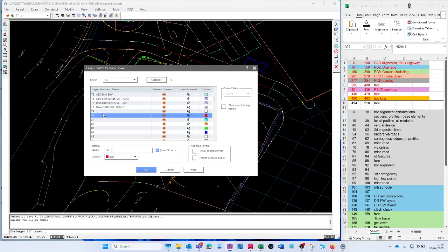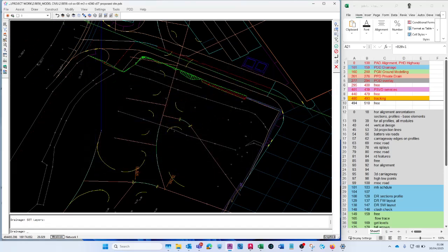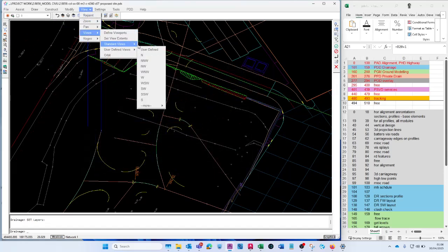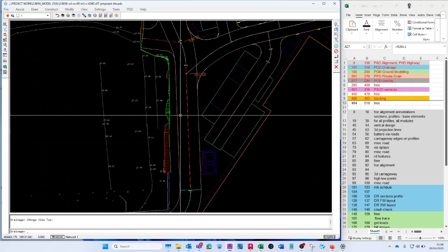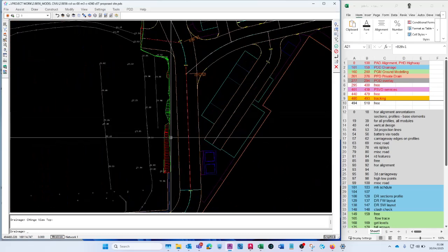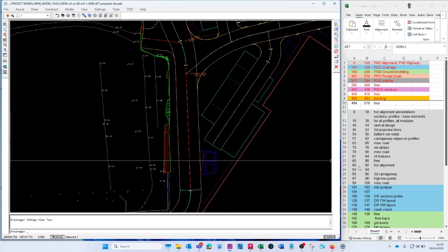so 79 to 80, just some miscellaneous ones. 81 to 84 get used for your features when it's creating those features for your roads. Then you got 85 to 89, some more free layers. Laybys, self-explanatory. If you did a lay-by along your road, it creates it in the default layer. It would draw a lay-by, saying maybe you have a lay-by here for 3 parking bays. It would generate those lay-bys on that layer.